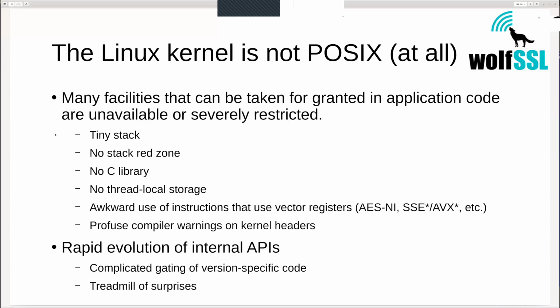And if you overflow the stack, you are doomed. That is a very important objective for us in development: to make certain that our runtime will never challenge that 16 kilobyte stack. You'll see in a later slide what the stack high water mark is for many of our self-tests. But rule of thumb, we're typically not going to go past 4K, and often we're going to be significantly smaller than that.